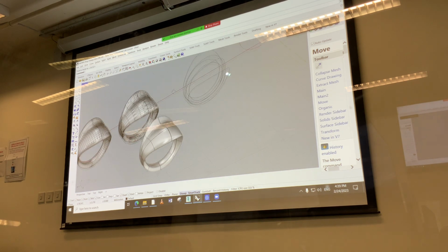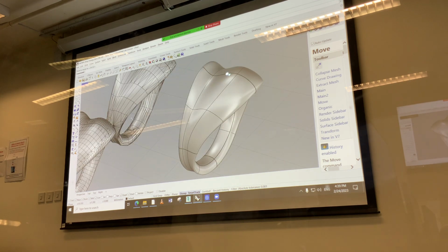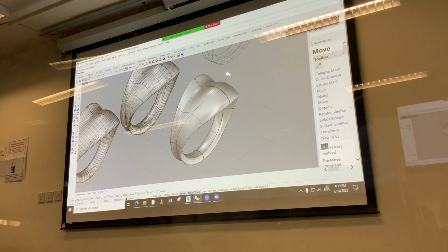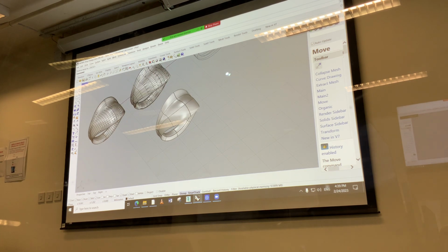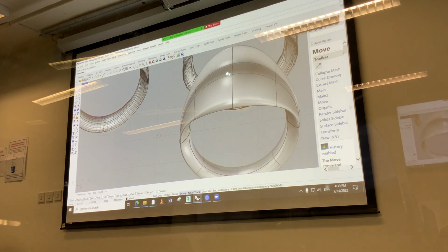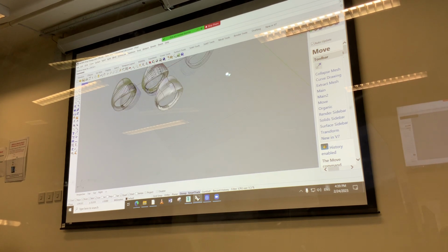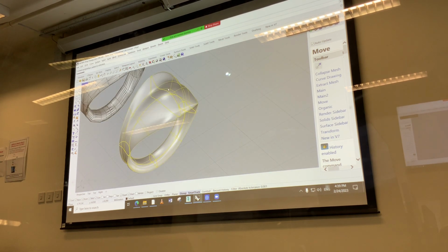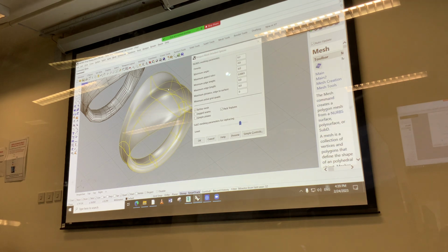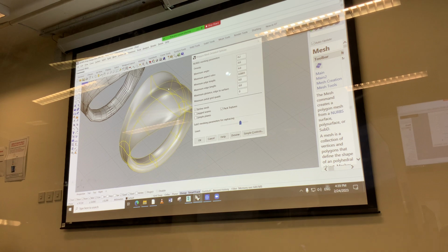The other problem that we have with this jaggedy mesh is that we still have a lot of triangles, and these triangles are very annoying. Again, ideally, our goal in the end is to have a mesh without a single triangle. So we have to go back to the mesh. This is really an art form where you will see, if you make the right decisions here, they will carry on all the way in your design, all the way. And you can never go back to it. So you have to spend some time on it.